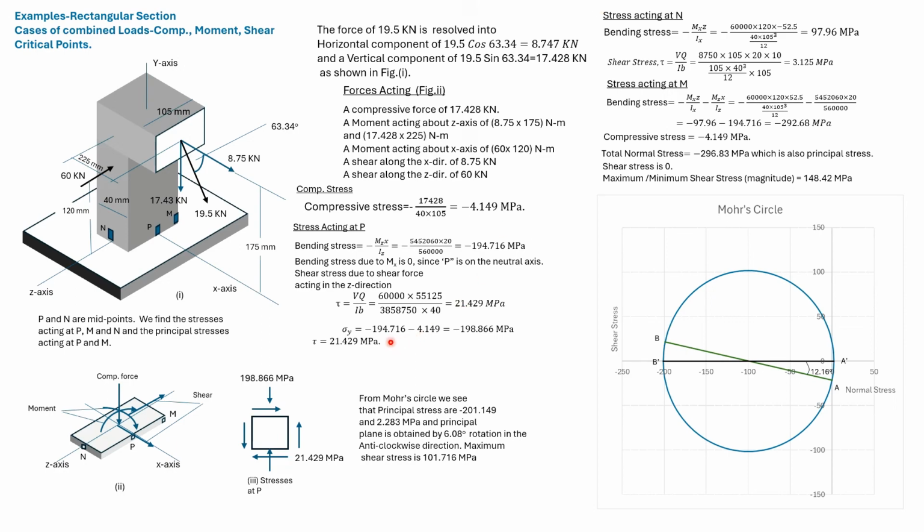Here we have added up the compressive stress due to the compressive force and due to bending. The point N is subjected to tensile stress due to bending about the x-axis. It is also subjected to shear stress due to this shear force.